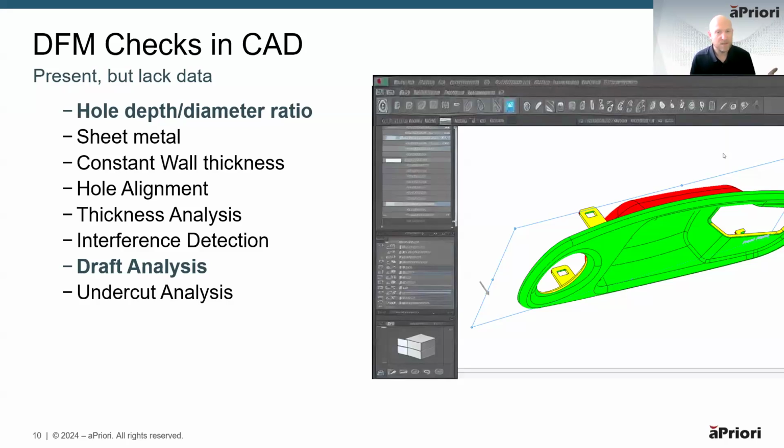But what do I use? What draft angle do I need to check for? Are overhangs okay? What wall thickness is acceptable? Finding that data to run the check is not always that easy. Often it's material specific or machine specific, it could even be supplier specific, or specific to the size of the part, depending on how deep it is.